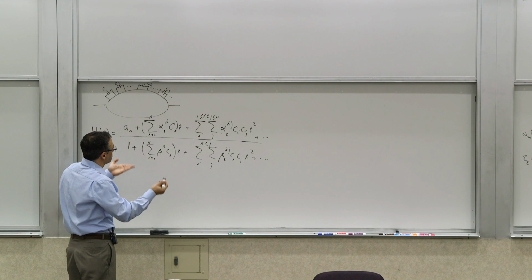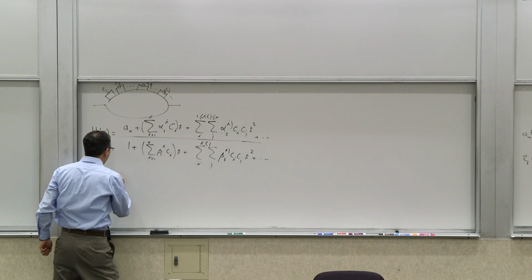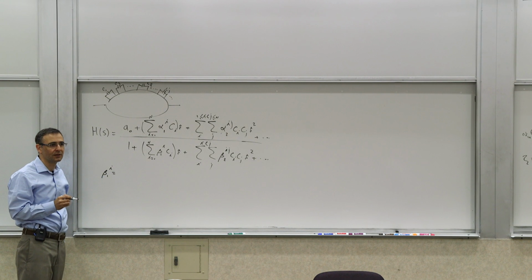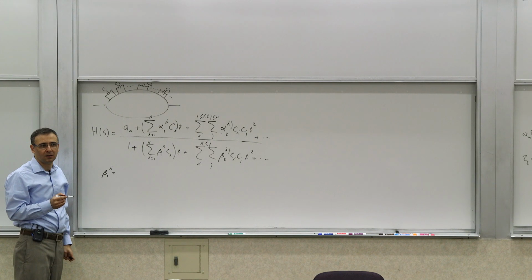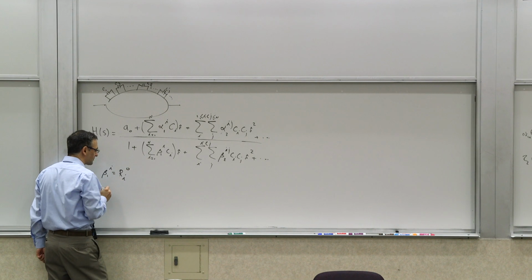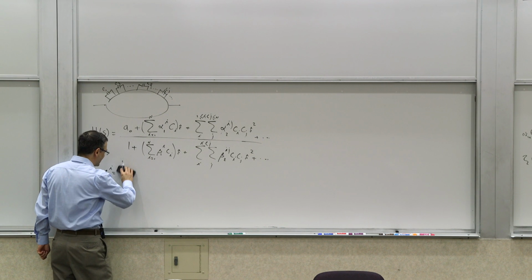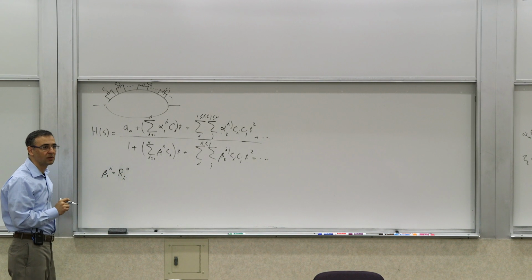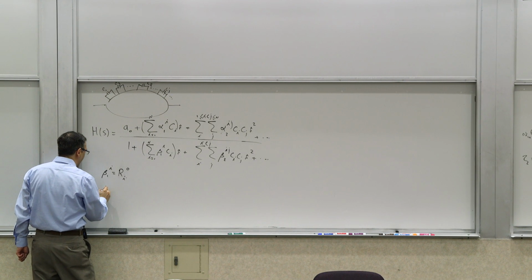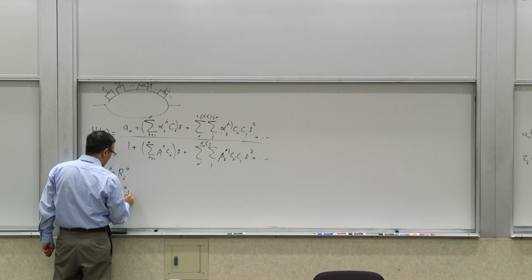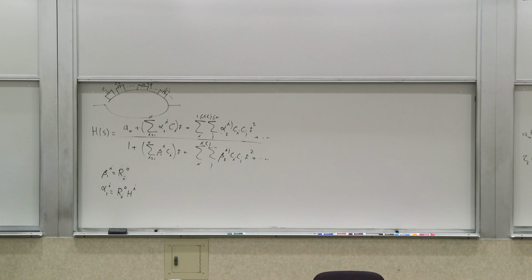Okay, so we did calculate these things. What was alpha? What was beta 1i, if you have just purely capacitor stuff? It's the resistor seen by the capacitor. It's Ri0. It's the capacitor resistance seen by element i when all the other elements are 0 valued. We did this part of the derivation. And alpha 1i was Ri1 Hi0. We had done these calculations. This part we have done before, so we can use those results.